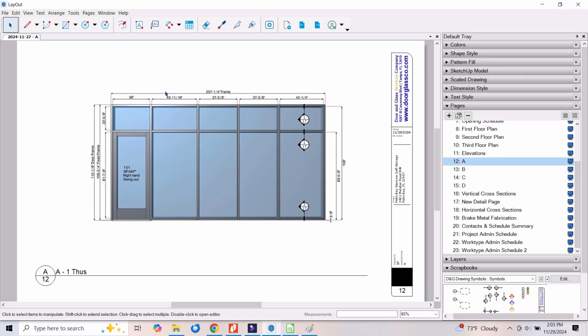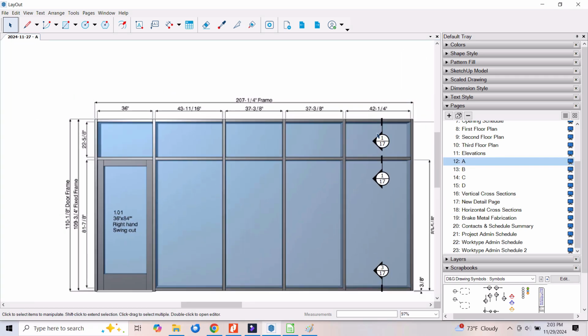that. Now, as a general convention, I'm placing the marker on the right, it's looking to the left, and I could indicate a cross-section across each one of these head components. It just makes the drawing that much more busy, and every single one of these is the same. If one of them were different, for example at the door transom, then I would show that as its own separate section. If I have all the same, these 3 vertical mullions, if they're identical, I'm going to use a single marker on the rightmost one.